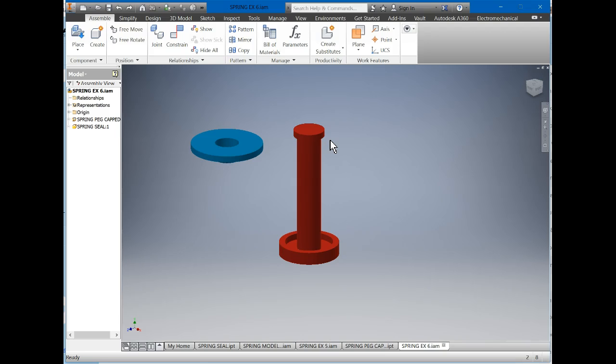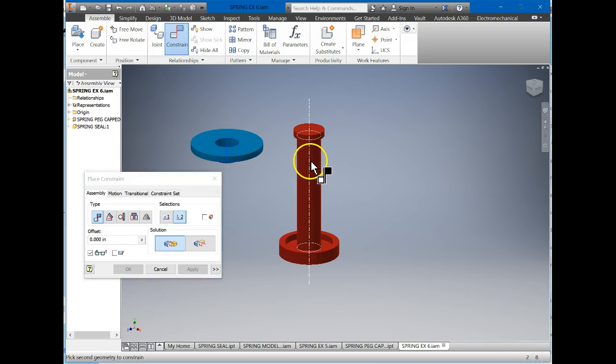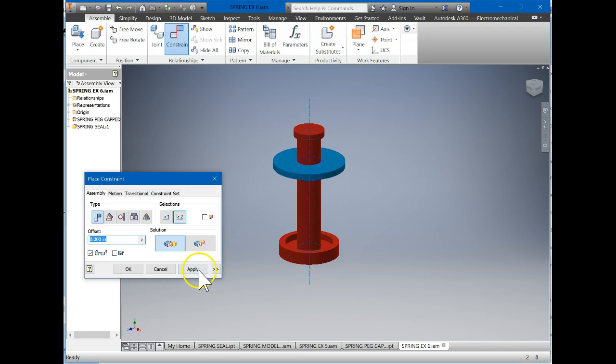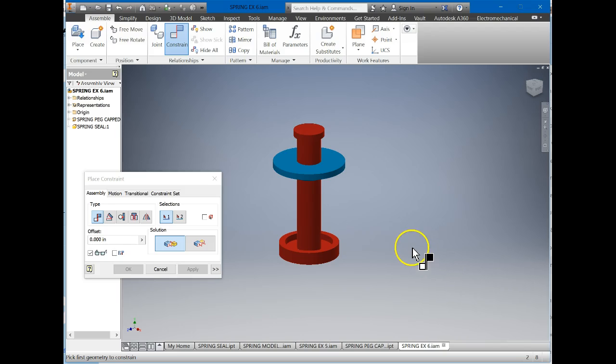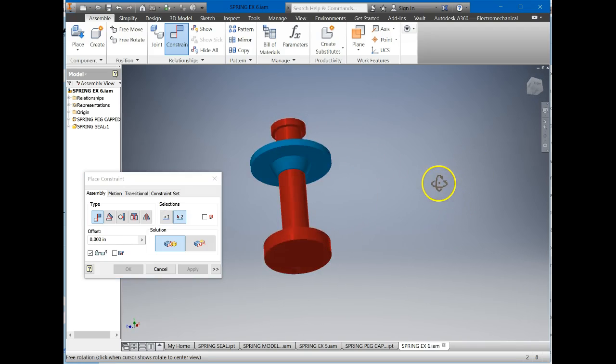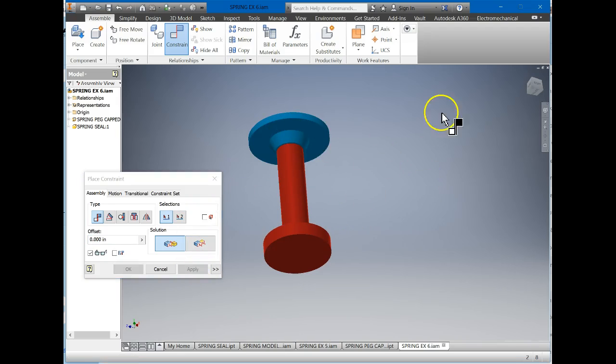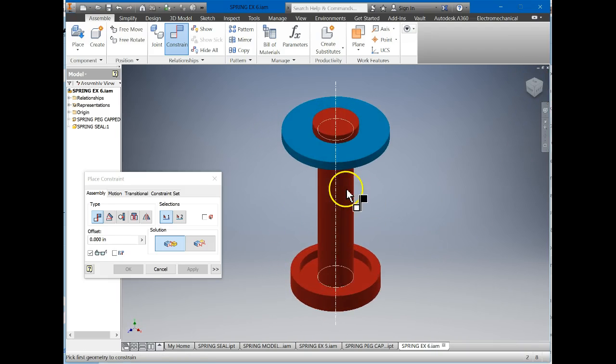So here I've got a model of what might look like the riser and the lock ring and the wiper seal. So we need to apply a constraint. So we can put the wiper seal on the riser, okay? And for this demonstration, to make it fast, we are going to apply a constraint between the top of the wiper and the lower part of the nozzle and attach those two. So now we should be able to see that it is nicely constructed.